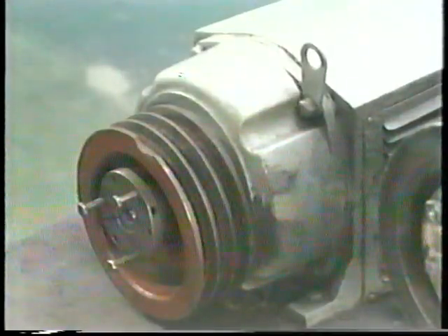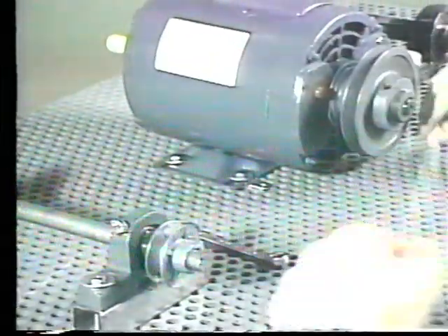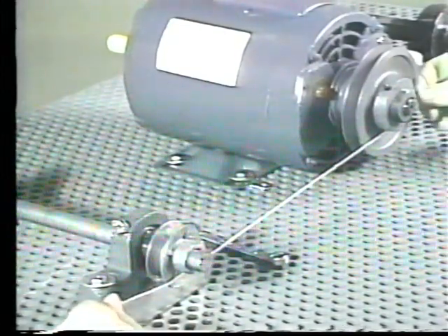In addition to tension, the condition of the sheaves and their alignment can also affect belt performance. If the sheaves have burrs or rough spots, the belt will be gouged and it will wear out faster. If the drive is misaligned, the load will not be distributed evenly across the belt. As a result, some parts of the belt may wear faster than others, and the belt will fail sooner than it should. To align the drive, stretch a clean white string between sheaves or use a straight edge.